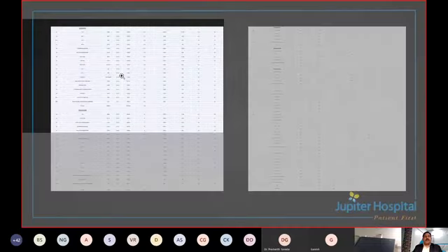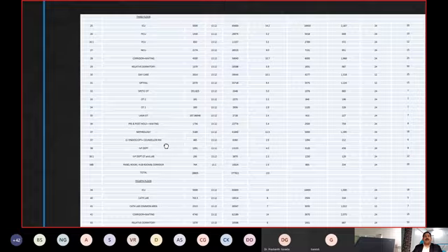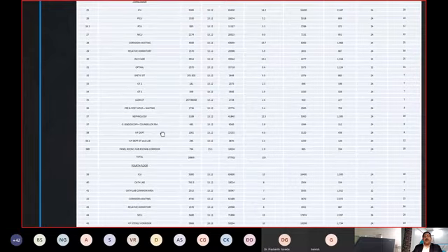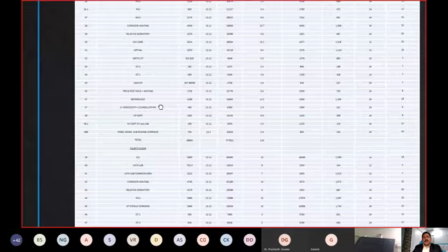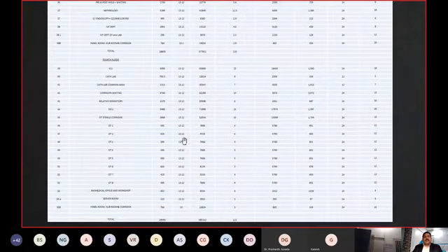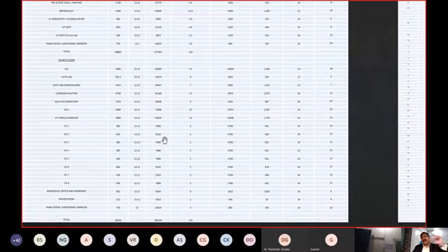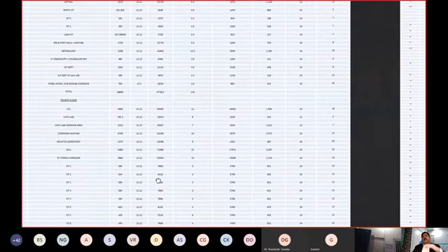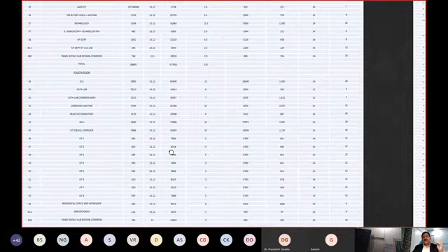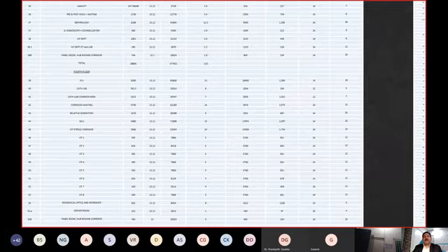Okay, now again I will zoom in. Here we come to the second and third floor where all these ICUs are. When I say all OTs are there, the main OT complex is also here. If you see, this is the height: 13.12 is the height without the false ceiling. The false ceiling is always at 10 feet. Normally everyone puts a minimum of 9 feet, but we prefer 10 feet, but the real height is 13.32.